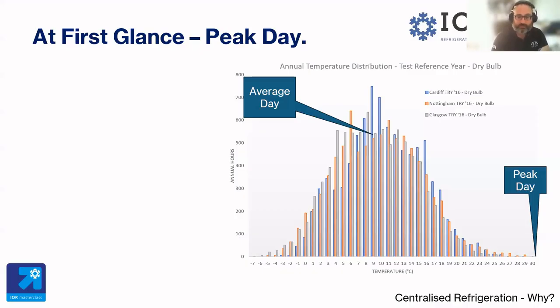99.99% of the year, we are operating at what I consider peak part load. And this is where our 2 theoretical refrigeration installations will start to operate differently. We're going to start to see lower dry and wet bulb temperatures. We're going to see less product throughput and less associated door openings and personnel and lighting loads, etc.